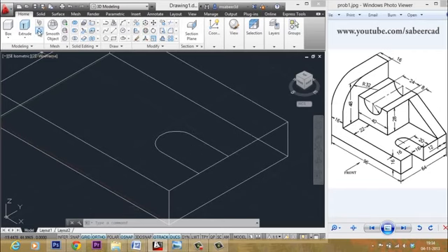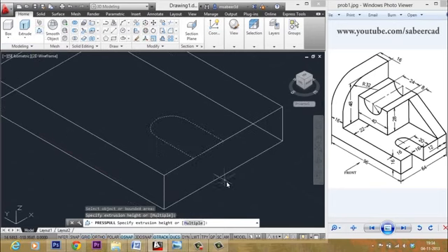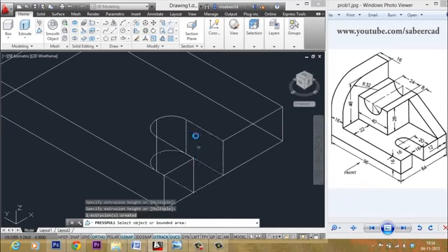For that, you can just go to the press pull tool, pick a point inside, and drag the mouse all the way down until it crosses this thickness. Then you just leave it. It has automatically made a cut. You don't have to subtract it because that's the use of press pull. Now you can erase this bottom profile which you drew first. That's not required.